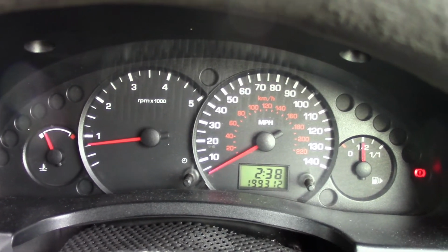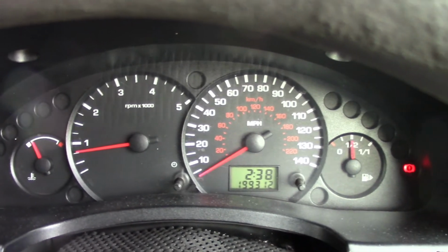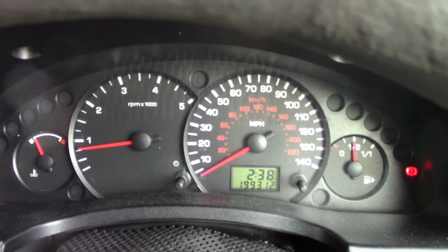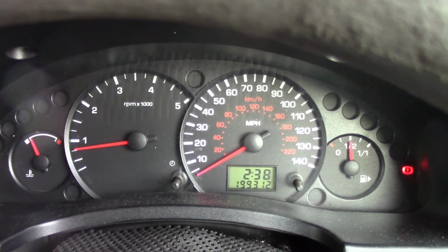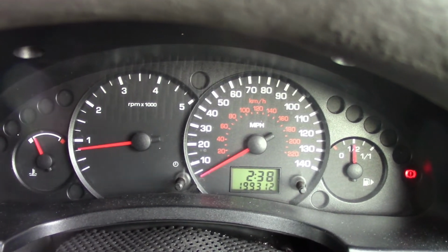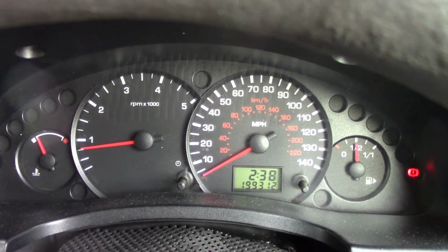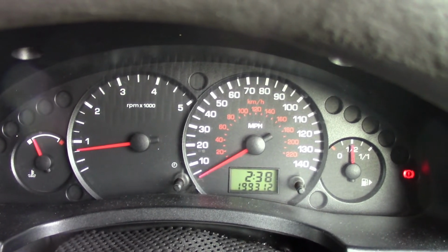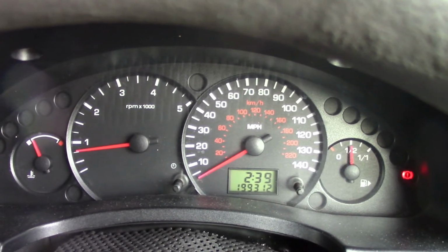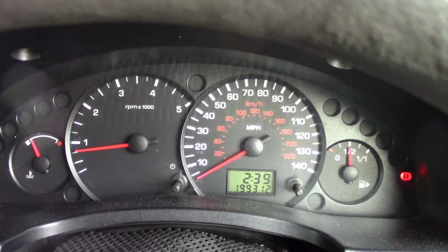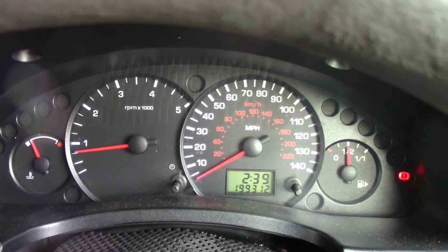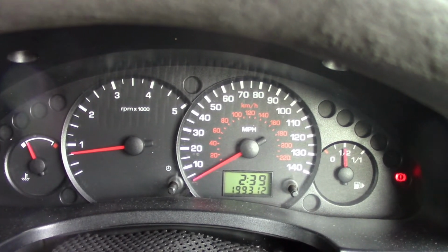Another issue we had with the car while I took it on the test drive: on the speedometer the speed reached 35 miles per hour, but on the scanner we only had 11 to 13 miles per hour, depending on the variation of the speed. So there was a huge difference between the vehicle speedometer and the data taken by the scanner.